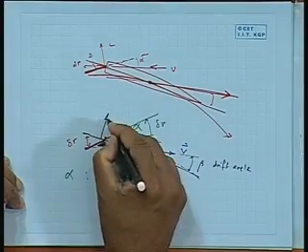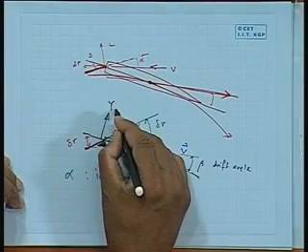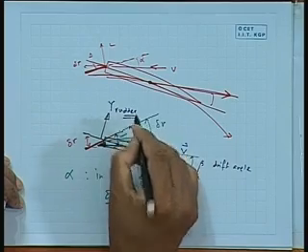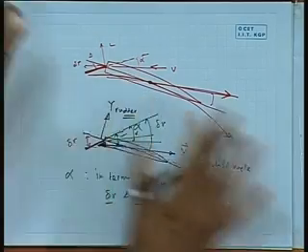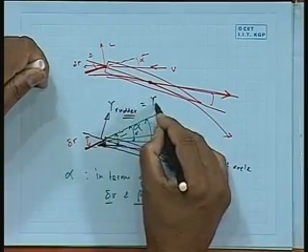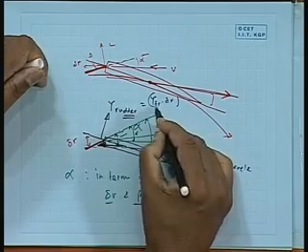Once you know the angle of attack, obviously you can find out CL and CD. Once you know CL and CD, you can find out the total forces coming on that, and from that you can find out my net y force, because ultimately I want to find out, with this as my x axis here, the force coming along the y direction, that is, what is my y rudder. You can find this out in terms of CL, CD etc., and this y rudder is y delta r into delta r, therefore, from there you can find out y delta r.